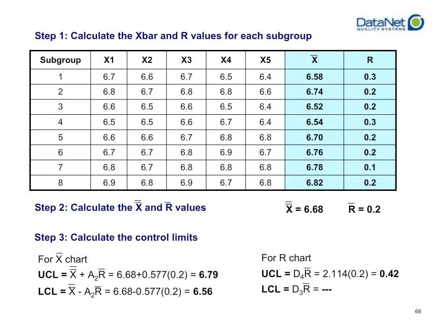If you had a lower control limit, which in this case there actually isn't one that is applicable, you would multiply your D3 value times your R bar. In this case, it doesn't actually have a meaning, so there's no valid lookup for that, so you're not going to get a value. It's undefined. Another thing to keep in mind is just a quick sanity check. Your range is a magnitude. It is how big your largest from your smallest values are. You should never get negative values. You should never be able to get a value that is below 0.